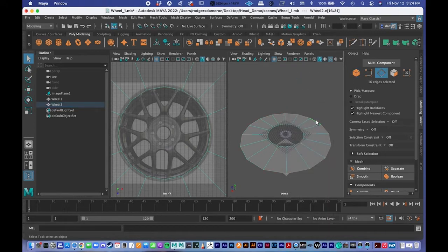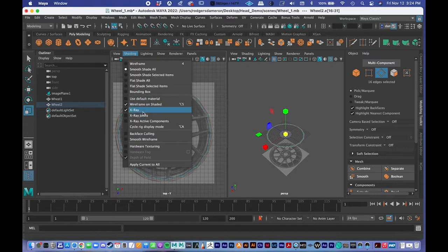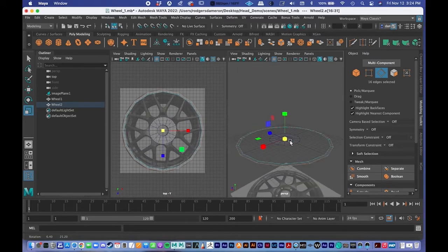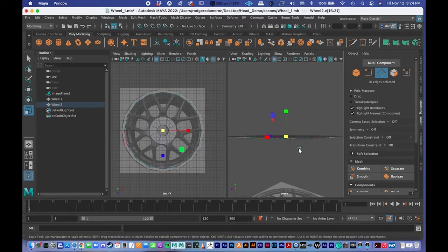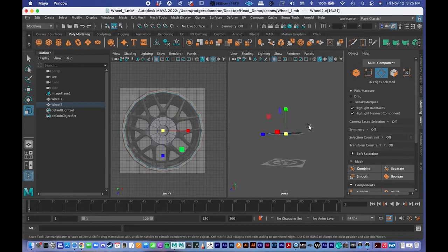So right click and go to edge mode. And select that outer rim. And again, you can just do that by double clicking. Then I'm going to press the scale button and drag it in. One really important note here is this technique I'm working is helpful and it saves some time. But if you don't change the anchor point to that center point, this technique might get a little sloppy for you. You can still do it, but when you scale it up, it's going to scale up vertically too, and this keeps it so it scales flat, the fact that we had changed the anchor position here.